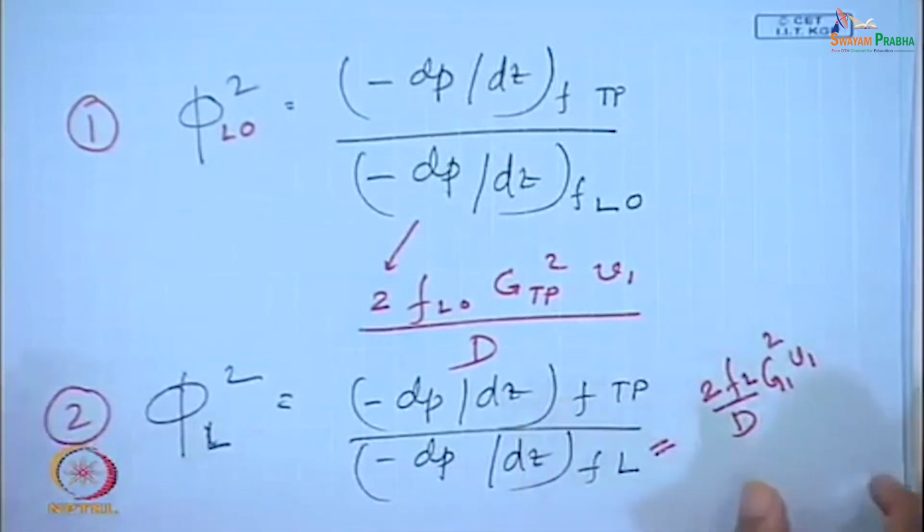We would always like to express it in terms of a frictional pressure gradient which we can easily measure, or rather for which we already know the analytical expression. Single phase pressure drops are very well known. So, we can define it in terms of equivalent single phase flows. How to define the equivalent single phase flows?